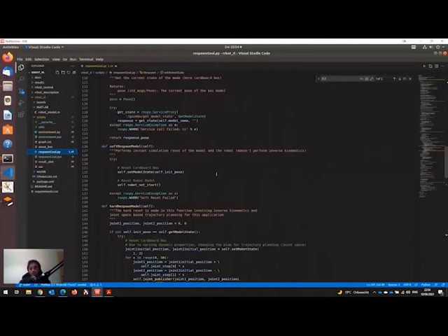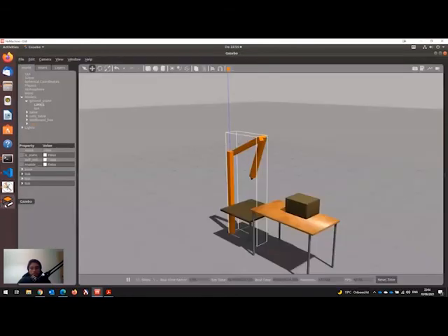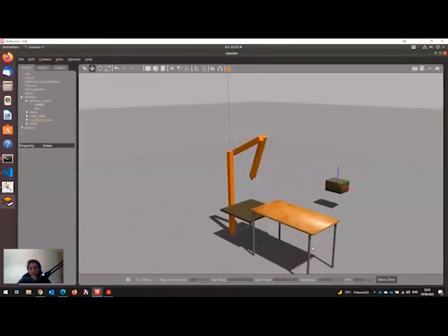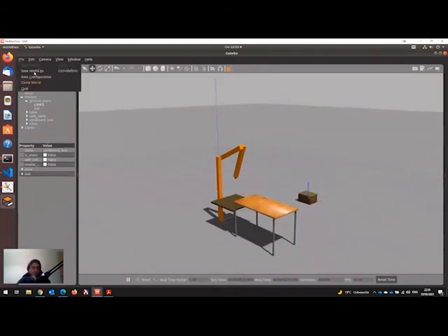This one doesn't use inverse kinematics, and we use this reset when, for example, the box was out of the reach of the robotic arm, so then it cannot use inverse kinematics and trajectory planning to get the box, because there is no configuration to go to that position basically.